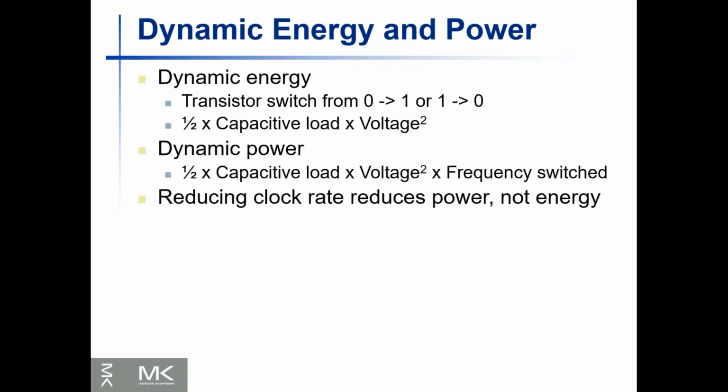Okay. And if you look at this equation, how can you reduce this power consumption? One is to play around with the capacitive load. Unfortunately, once you have the fabricated processor ready, the capacitive load can no longer be changed. It's part of the process. So you have to work on a different transistor process to have a different capacitive load. But things like voltage and frequency can be adjusted while the processor is running. So this is where you have dynamic voltage and frequency scaling.